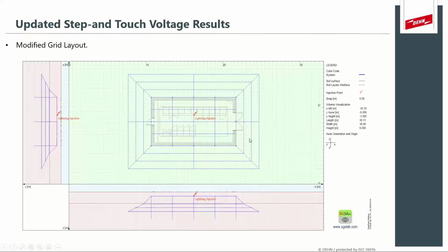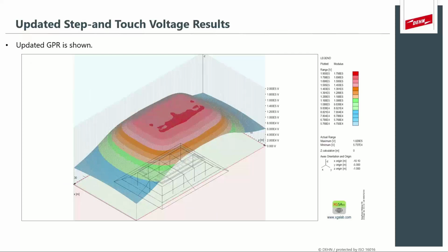You can see that we apply these rings around the grid at different depths, and we start controlling the ground potential rise curve and the steepness of the curve from the top all the way down to a safe distance away from the building. Now, if we inject the same 50 kA into our new grid for very high frequency, you can see that we've suddenly established our equipotential plane. So there are not a lot of big differences in voltages on this graph that can cause step voltages.